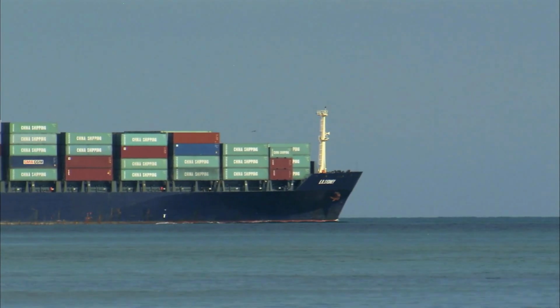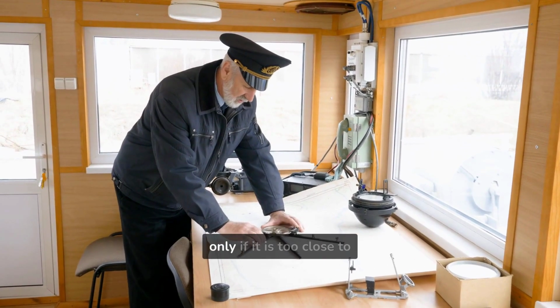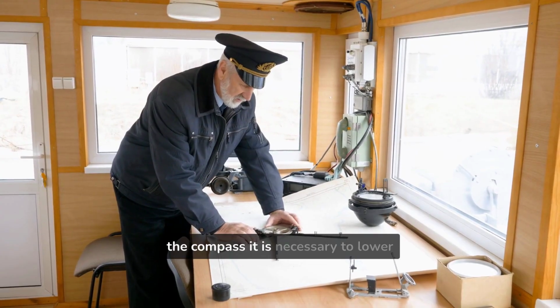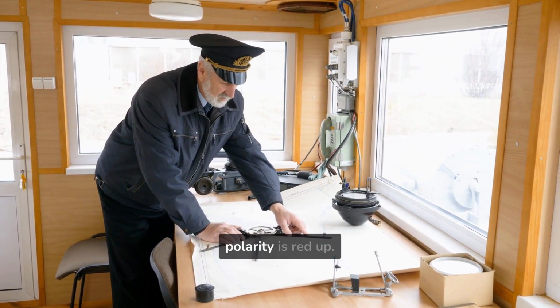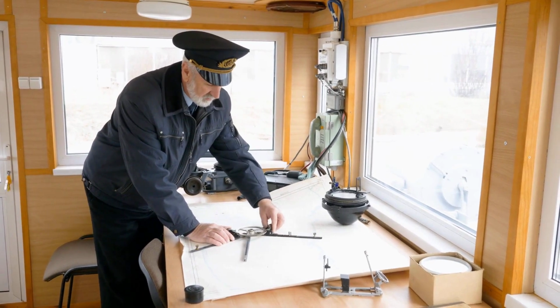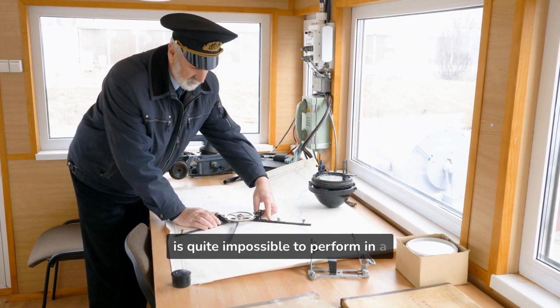1/ The heeling magnet should be checked, though it is better not to change it. Only if it is too close to the compass is it necessary to lower it so as not to affect the compass. Normally the polarity is read up. So, avoid the adjustment of the heeling magnet, which is quite impossible to perform in a merchant ship.